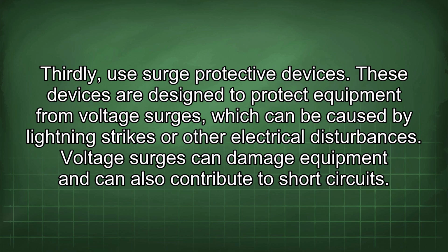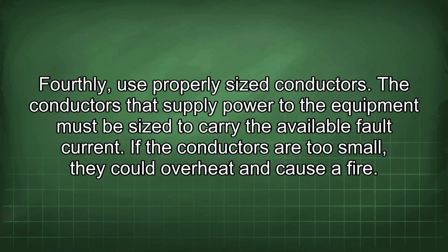Thirdly, use surge protective devices. These devices are designed to protect equipment from voltage surges, which can be caused by lightning strikes or other electrical disturbances. Voltage surges can damage equipment and can also contribute to short circuits. Fourthly, use properly sized conductors. The conductors that supply power to the equipment must be sized to carry the available fault current. If the conductors are too small, they could overheat and cause a fire.